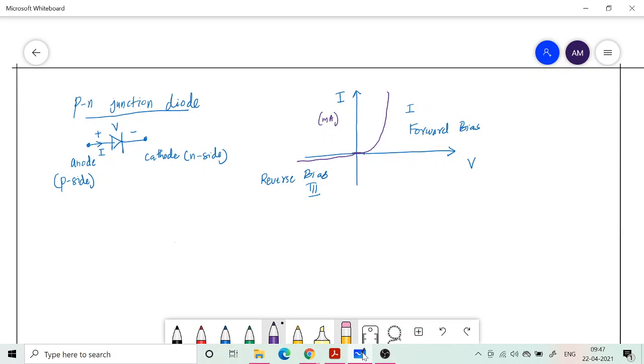So if you take milliampere scale and plot this IV characteristics as you apply voltage, in order to see any significant current, when you plot the current in milliampere scale, you need to at least apply some 0.6 volt. Okay, so when you reach 0.6 or 0.65 volt, that's when the current begins to rise, and once it goes beyond 0.6, then the current exponentially increases. Okay, so this 0.7 volt is sometimes taken as the cut-in voltage. So this is what is referred to as the cut-in voltage.